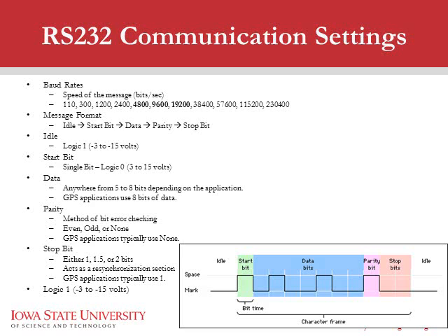The message format is the type of data that's transmitted with each individual character of GPS data. Things to consider here is that the GPS application always uses 8 data bits. So when setting up the GPS unit, or the receive unit, we typically would use 8 data bits, no parity, and 1 stop bit. This information, these setup pieces, will be specified by the GPS receiver and must be correctly set in the GPS display in order to enable communication.